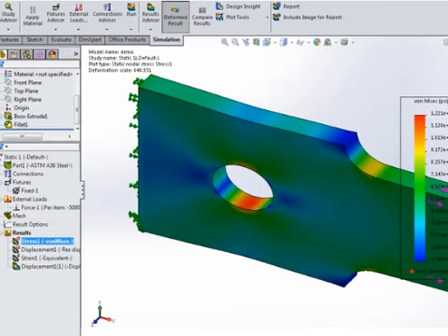Short of that, the other thing that you can do is apply a fixture to that hole, right? Instead of applying the fixture over here on the left end, a quick and dirty way to do this would be to apply the fixture just on that hole and then apply a load to that. Now, that's not exactly right because in real life, only half of the hole is going to be interfacing with the pin, because the pin is either going to be pushing to one side of the hole or to the other side of the hole. But it's a way that you can at least get somewhat close, maybe.